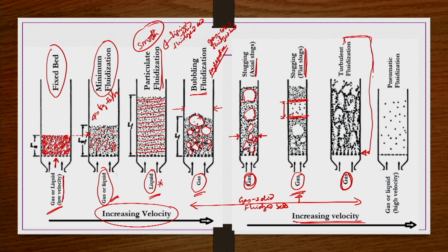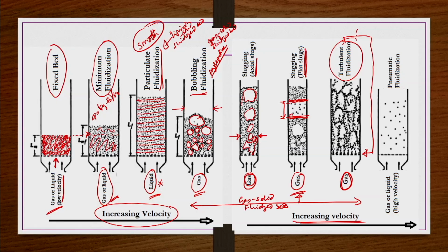Okay. So circulating fluidized bed, that is known as particle recirculation is there here. So these kinds of beds, if you do not have recirculation of the particles, then we call them turbulent fluidization. If you capture those particles and send them back as a recycle to the bed again, then you can call them circulating fluidized beds.